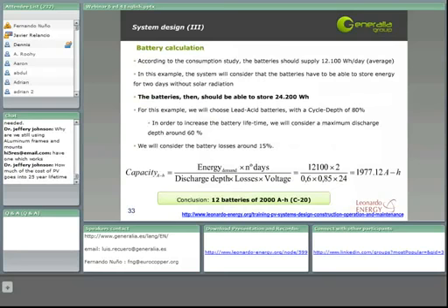So, as a conclusion, as 1,977 ampere hours is not a commercial size, we can get 12 batteries of 2,000 ampere hours based in the C20 profile. This means that we are getting the profile that the energy will be discharged in 20 hours.